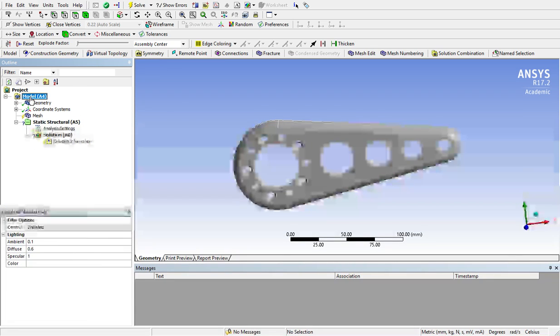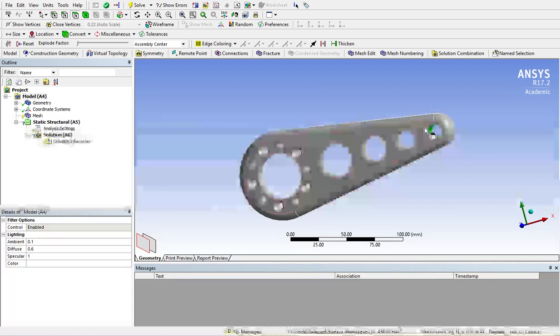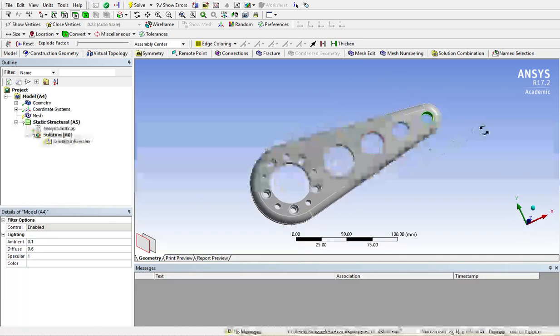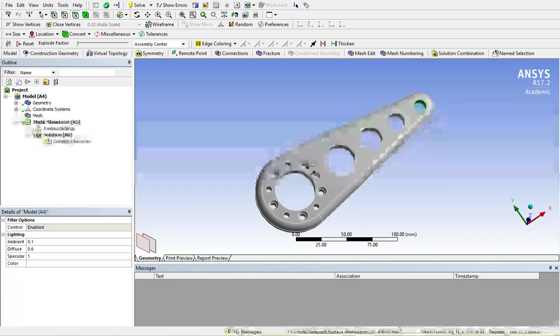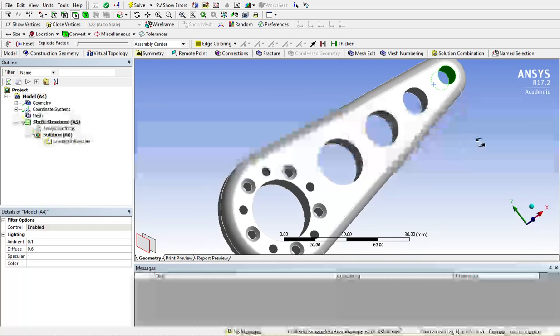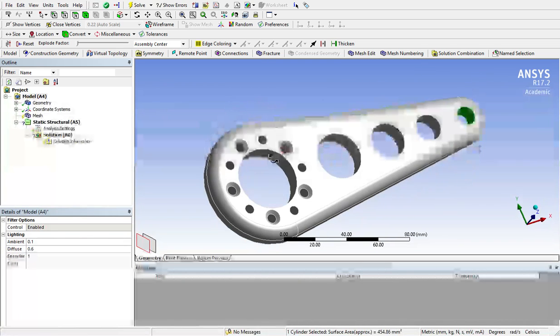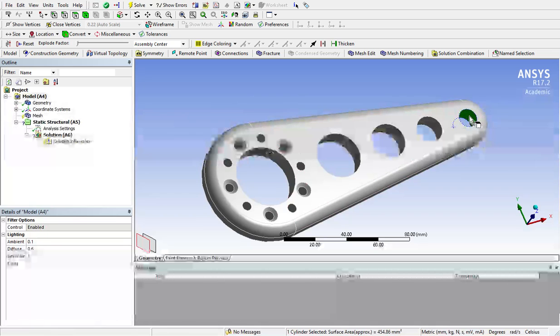You also need to put in the remote force. In the assignment, you'll know that the concentration of force is actually 50 mil away from that very back edge of this surface here. So if you want to just select the inside, let's see if I can zoom in. Right, yeah, there we go. You can just about see that, if I can wiggle it around a bit. There we go. That bit's come up in green, that's selected.